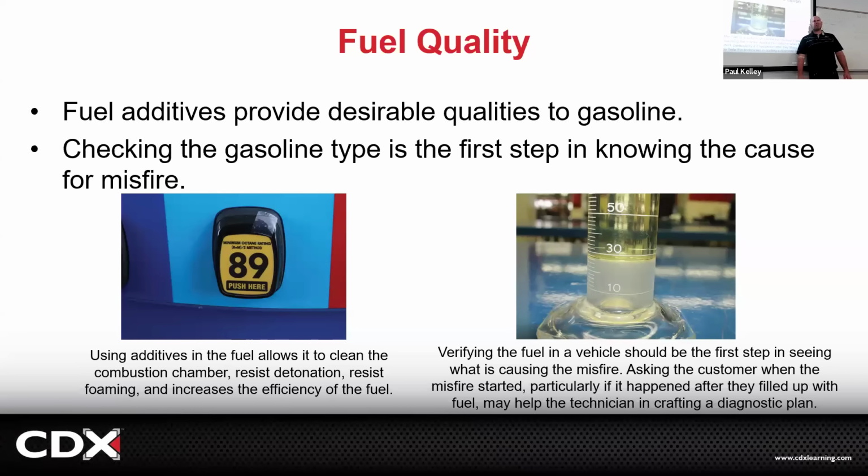So this guy cut it straight with me. I'm like, you know what? I know what tools I'm going to bring: a 5-gallon bucket that's empty, a couple tools to undo a fuel line, and my scan tool. So sure enough, I go to crank it, go to start it, won't start. I pop a fuel line off. I take a water bottle. I go in my scan tool. I command the fuel pump on, and the fuel pump runs.